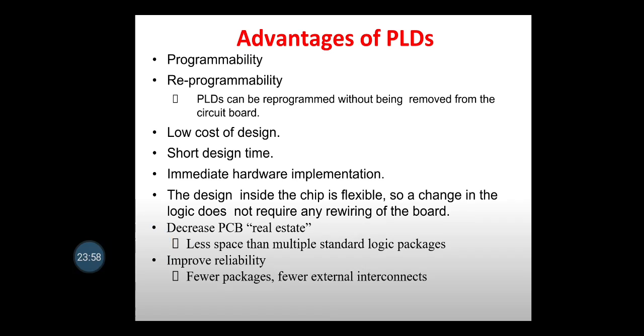Advantages of PLDs: programmability, reprogrammability. PLDs can be reprogrammed without being removed from the circuit board. Low cost of design, short design time, immediate hardware implementation. The design inside the chip is flexible, so a change in the logic does not require any rewiring of the board. Decreases PCB real estate, less space than multiple standard logic packages. Improved reliability, fewer packages, fewer external interconnects.